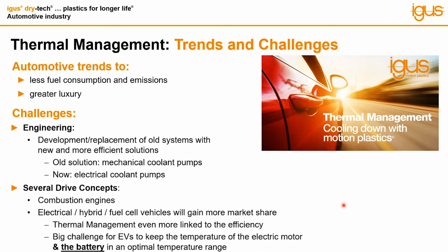Especially for the electrical or for the alternative drive concepts, if we sum it up, the connection to the thermal management is even higher connected to the efficiency of the vehicle, because now you don't have to just focus on the motor and the engine or the interior comfort. You also have to focus, cool down, heat up, and reach the optimal temperature for the battery. And this is a big part and a big challenge for the thermal management.